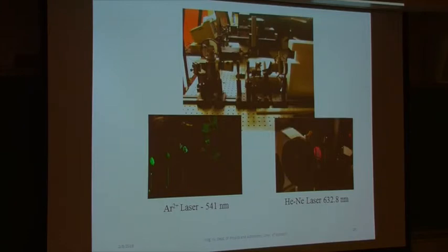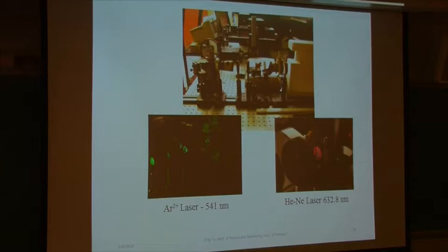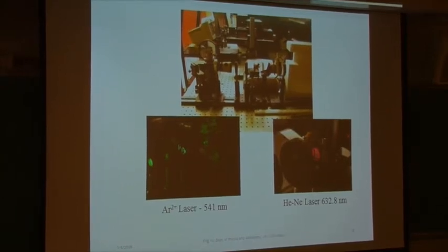What we need to do is treat the projector to tell it that everything's okay. For example, when we remove the light bulb, we put a resistor up there. And when we remove the fan, we put another resistor over there. And there's another sensor for the cover, so we put something that presses that sensor. So everything works, it just tells us that everything's okay.